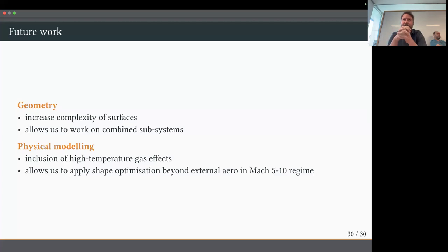A combined subsystem, for example, might be both the forebody and inlet system of a hypersonic vehicle, because as I mentioned, the forebody is some compression to your inlet system, and your inlet system is a large amount of your lift. Together, they want to provide some lift, and they do want to provide the right compression. So it looks like a good synergy that could be explored with design optimization. Maybe designing the systems in tandem or at the same time will lead to a better outcome than treating them as separate systems that we have to put together.